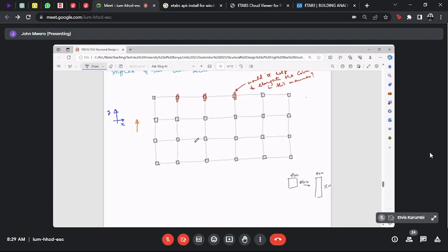Deflection is something that you will extract from your models once you have done the models. We'll get to that point, and you'll extract deflections, and you'll see as part of the outputs that I want us to do in this exercise, just by, for example, changing the column from an 800 by 800 to a 400 by 1600 in that direction, how much reduction of the sway, we call it the sway, the deflection, you're able to achieve.